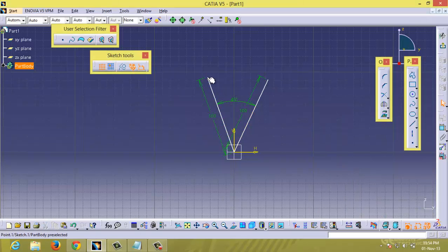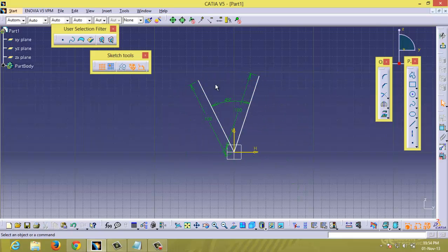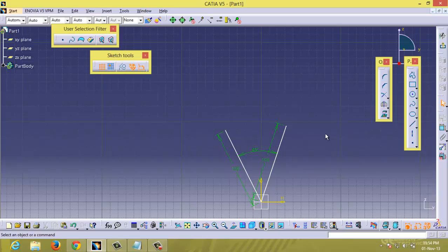So the angle is constrained, and wherever we make a rotation, the whole system is constrained and undergoes a complete rotation. Okay, whenever the forward and backward time ratio is the same, the connecting rod and crank will align in the same line at the maximum rocker position and the minimum rocker position.